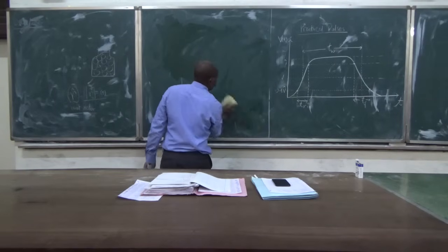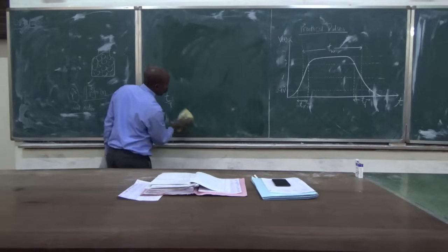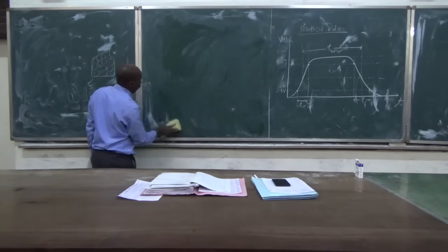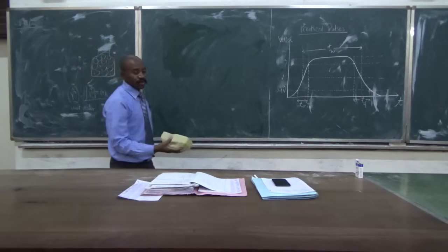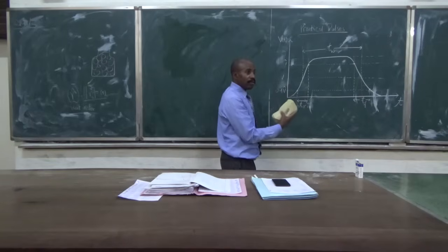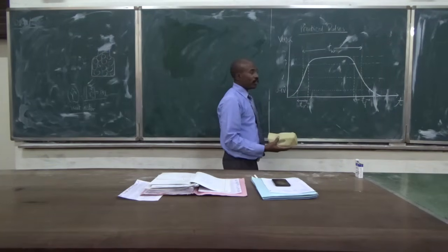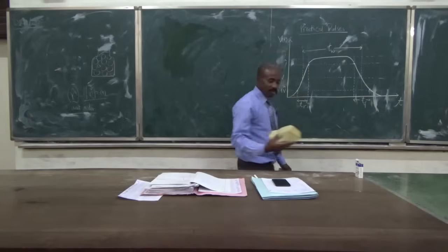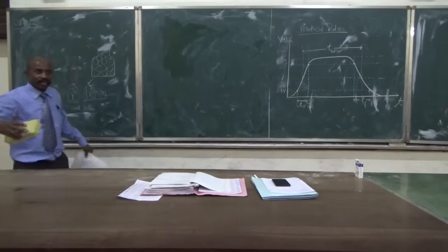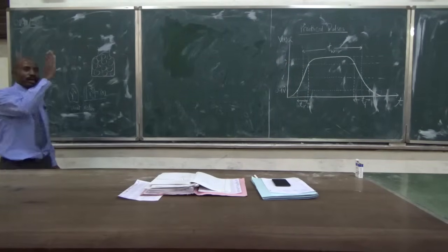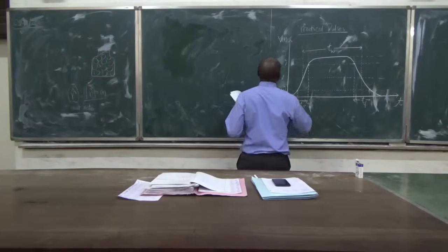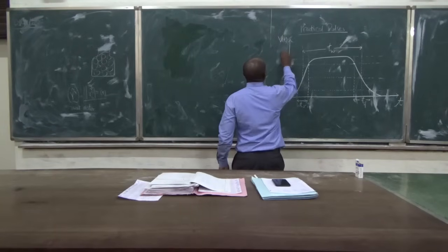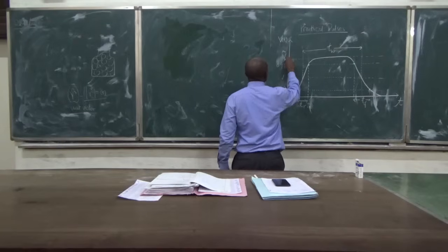So a good pulse should have the rise time very short. Yes, because the steeper you get, the shorter you get. The more slanting you get, the more you are expanding it, and that is not good. You should be able to have your on, off. So we have the amplitude, our 0.9 of the amplitude, of the peak value.